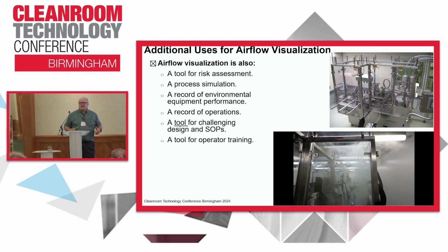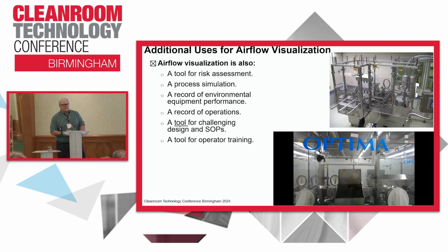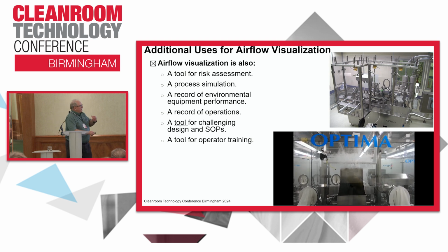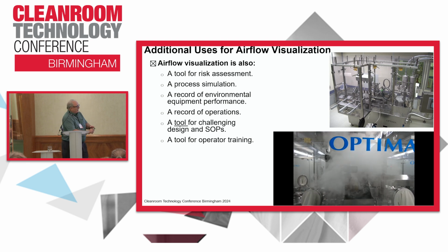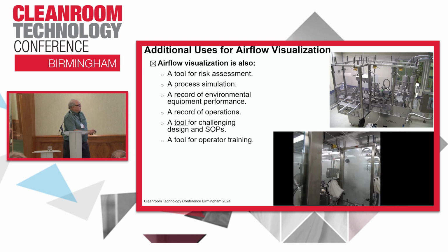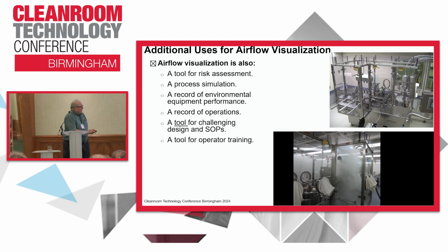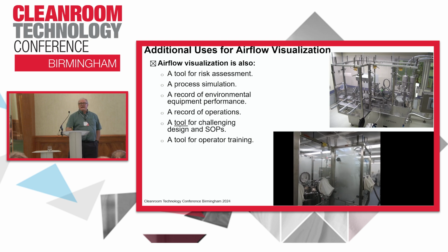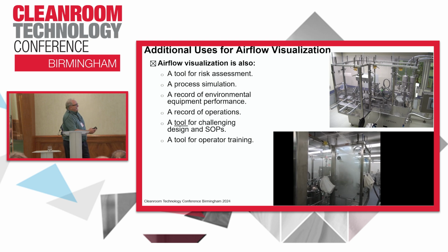The company got in touch with us because they failed their first media fill. They had a panic. They reached out to the owner of our company, who was a microbiologist, a mycologist. We took a look at it, and we identified they had a serious problem with their airflow, particularly in the loading zone. We came down, evaluated it, and were able to identify they didn't have suitable airflow due to placement of lights and HEPA filters.